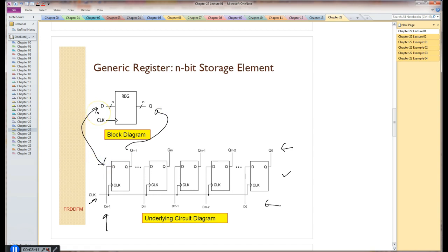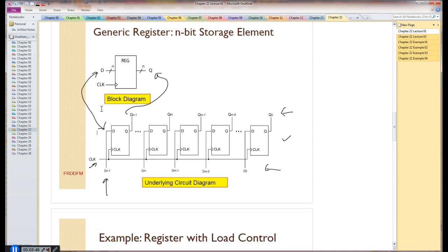These registers can be any width. They generally all work like this. Changes in the output are always synchronized with that clock edge. Once again, we can use the same vernacular as before, in that this element is going to store data. We consider it as the element latches the data on the D input into the memory elements of the register. So registers are extremely important. Probably half of all the digital circuits out there are a register of some type. So let's look at that.